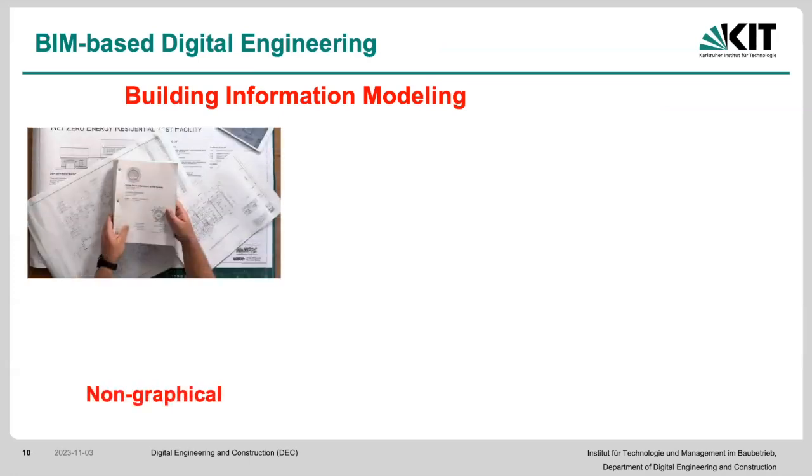So what is building information modeling? It's the combination or the linkage of non-graphical information, technical specification, that means material. So let's say one of the differences between a CAD and, if you want to add BIM to it, would be that a CAD element does not have information related to, let's say, its material properties. That by itself cannot be utilized for any type of engineering without adding that type of information to it, right? It would only be geometry.